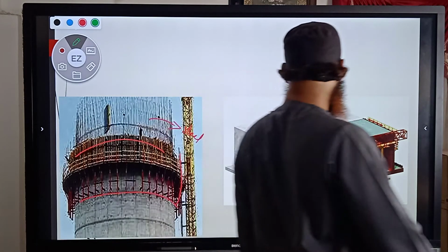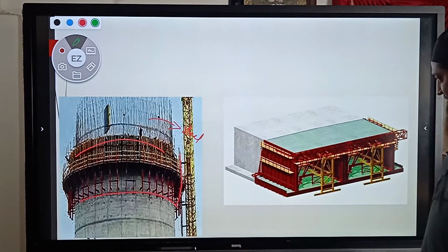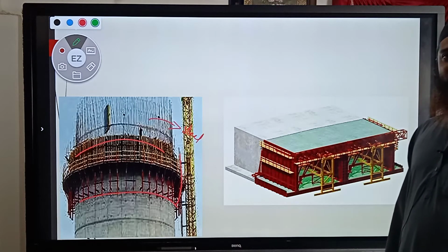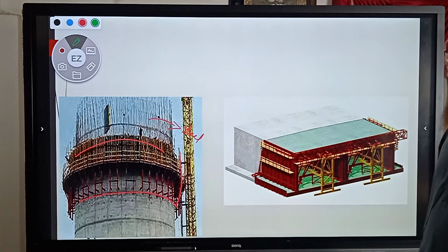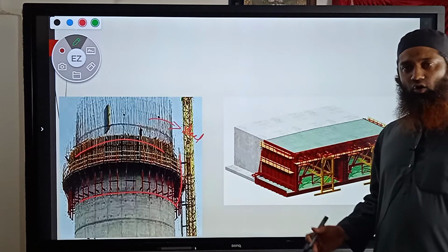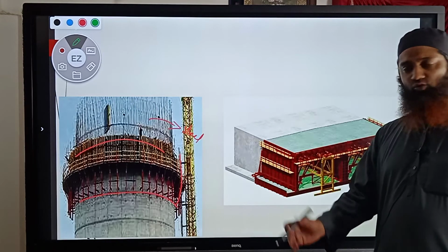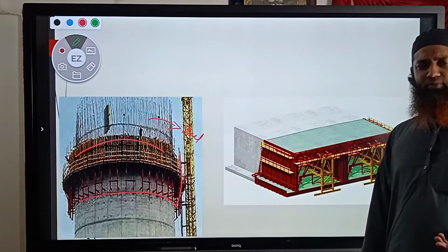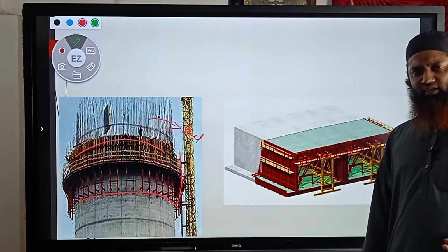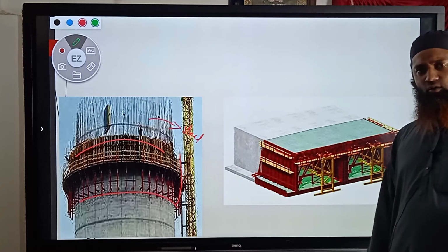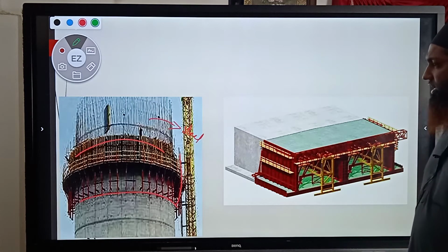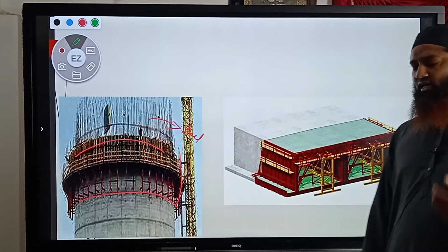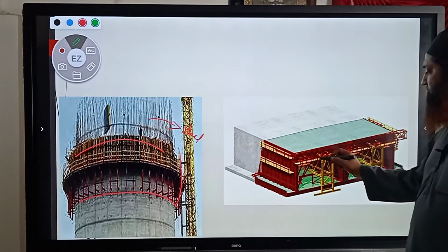And here you can see this formwork has been placed for a deck slab. This deck slab is placed at those places where we want free passage or movement of traffic below it. For the deck slab, as technology has increased, most of the time precast or prefabricated members are already casted in industry, brought to the site and placed here. Sometimes where there are no options available for precast or prefabrication of members, we go for erection of members on site only.